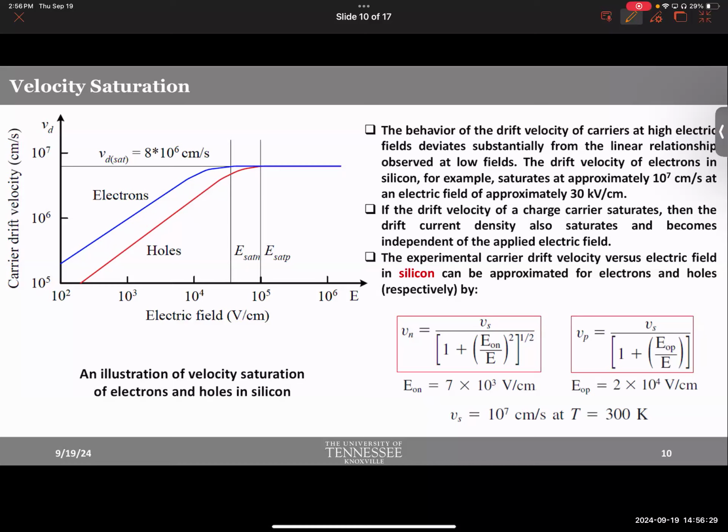Anyways, imagine you are trying to make the fastest MOSFET, or you don't even know MOSFET, I guess, say, the fastest transistor device. The faster the electrons flow, the faster the device is, by the way. So you want to make it fast, but it's not doing its job. You're trying to increase the voltage, but nothing's happening. Why? Who is the culprit here? They realized it was velocity saturation. And we'll get back to this concept in the MOSFET lecture as well. That led to a paradigm shifting decision in device design, when people discovered that velocity saturates in a semiconductor. And I'll tell you the simple reason.